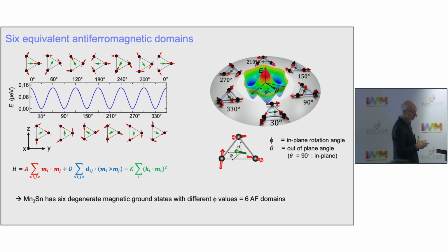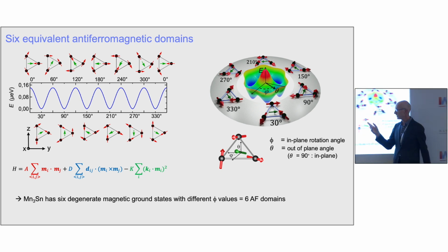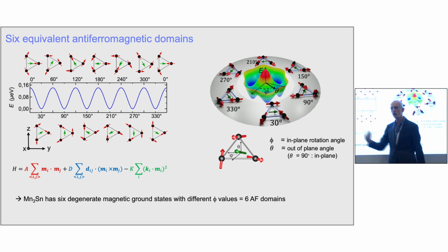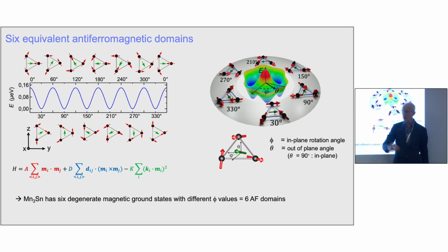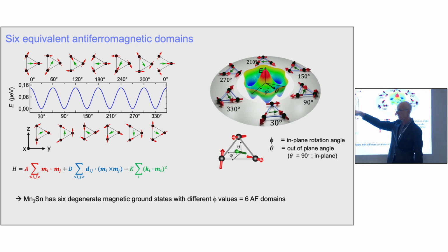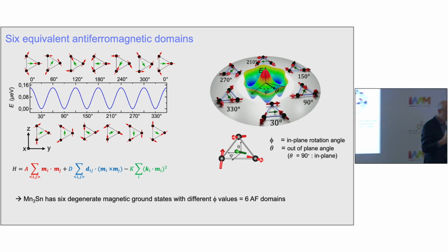It turns out that when we apply current, you apply torques on this system, and the torques will convert the structure from one of these low energy configurations to a high energy configuration. So when you remove the current, if it's exactly at that peak, it can go in one direction or the other, and you end up basically with a demagnetized system.